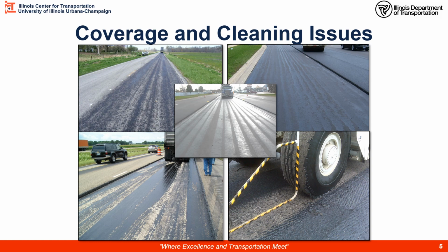And then when we do get a uniform coverage, it wasn't being allowed to cure properly and was being picked up by traffic, not only the trucks delivering asphalt material, but the material transfer device, picking up and cleaning right in the wheel pass where you need the adhesion to the new overlay the most. So we had good tack coat every place else, but not right where you need it in the wheel path. So these are some of the problems trying to be addressed by the update in specifications.